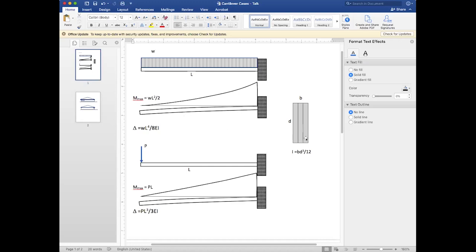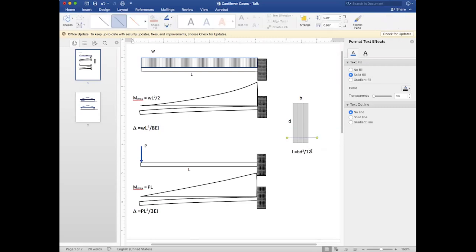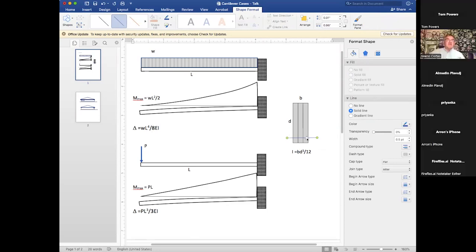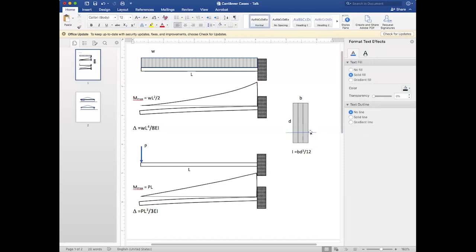So if I start to cut the bottom of this and remove the material below it, I'm taking strength out of the moment of inertia. So with a smaller moment of inertia, what will happen is the deflection will increase and keep increasing. The more cuts I make, the weaker the beam that I'm making. So that was something I had to contend with in this case.